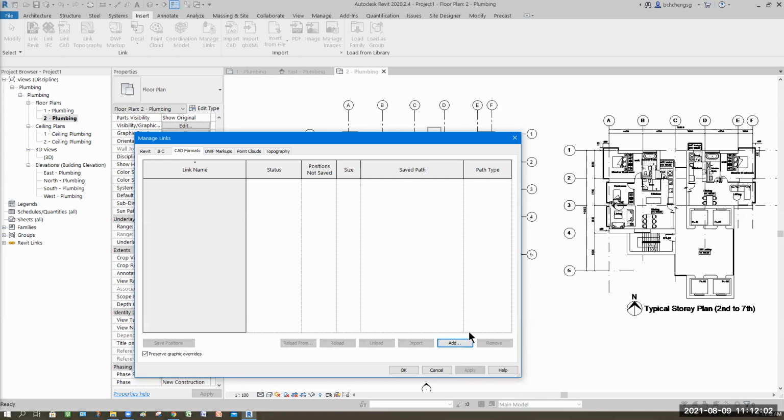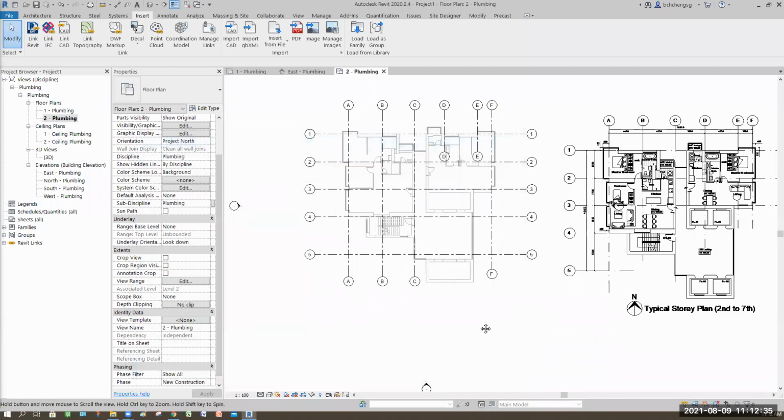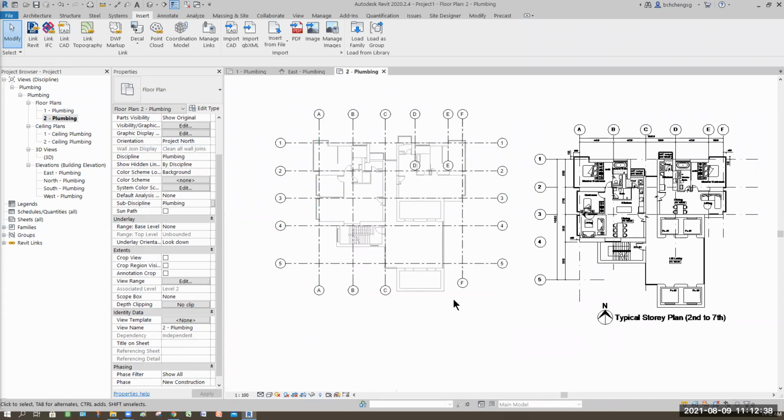Link is good in the sense that sometimes you still want to link for reference. You can have the link, then you can use unload, which means don't show. Only do a final remove when the project is completed, or unless certain things have been finalized and there's no need anymore, then you remove. Okay, so you need to understand these two portions. Later I'll hide this.